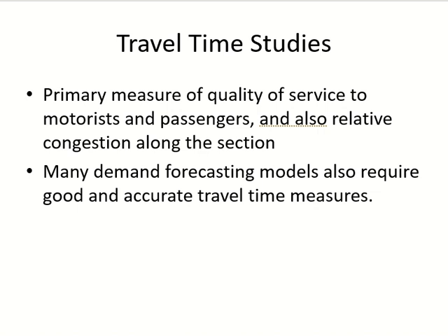Travel time studies separately. Speed studies, I showed you earlier as well when we were discussing time mean speed and space mean speed. For space mean speed, we have to take the entire segment. This is where we can do travel time studies. But we know speed can be for shorter segments as well. Speed can be for a point as well.